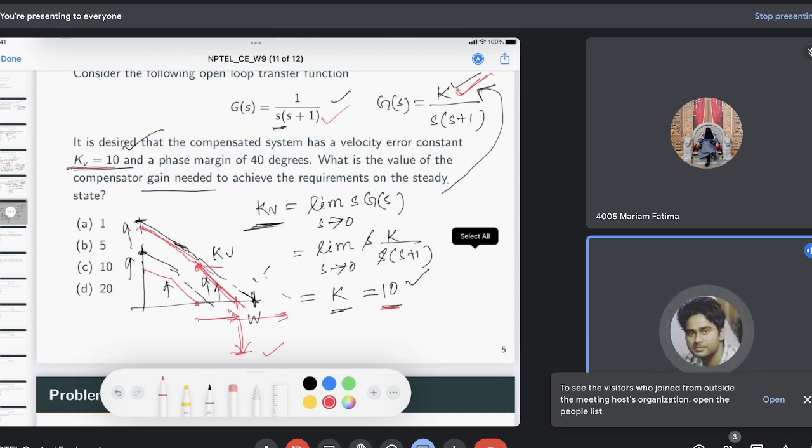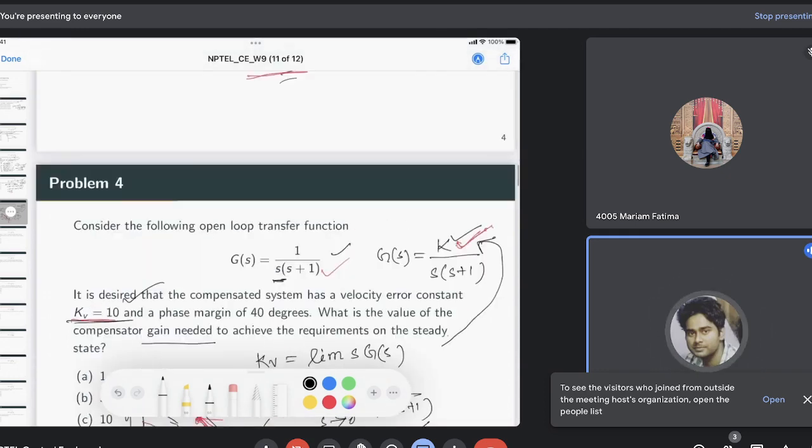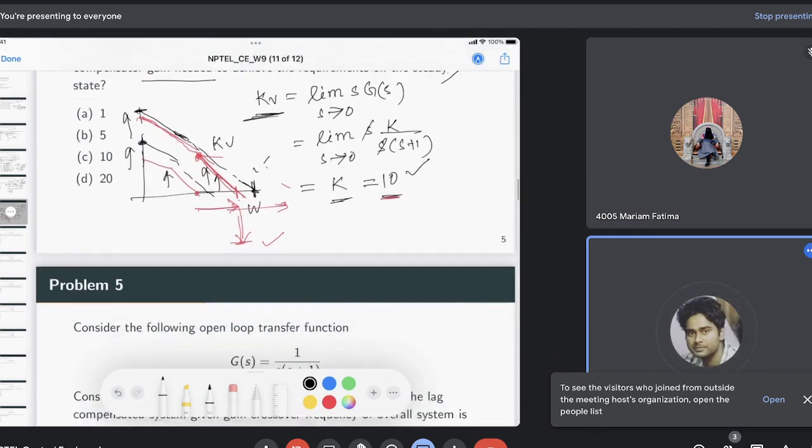So this can be verified using the Bode plot, just using MATLAB. You can plot and see that it is not meeting the requirement. I'm just explaining that intuitively. So we see that our phase requirement may not be met, so for that we will need this compensator.